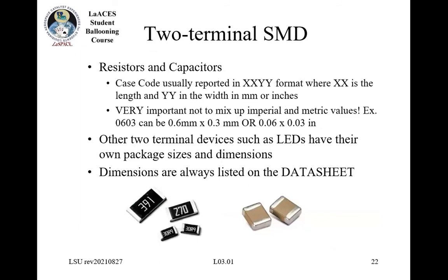And this is the surface mount. This is one example of a resistor and capacitor. These are very, very small. There are also different sizes. The 0603 is probably the smallest that you ever want to get. If you can get larger ones like the 0805 footprints or the 1206, you'll be a lot happier as a person soldering those than whenever you do the 0603.